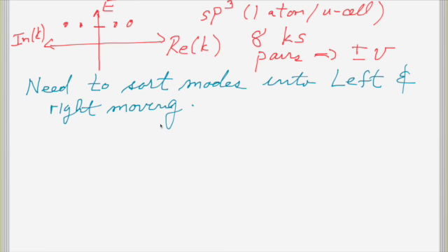Okay, and so the way you do this is, let's first think about the band structure of some typical direct gap, simple model band structure. You'd have a conduction band, and you'd have your 3 valence bands. Right, forget spin orbit and all that stuff. That'd be a very simple sort of model band structure, in our sp3 basis.